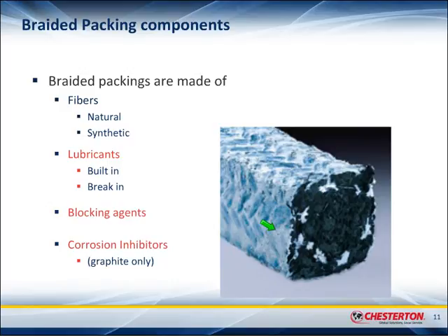What you have as well are break-in lubricants, and you can see break-in lubricants very well on this picture here on the right. That is the lubricant that is applied to the packing after it has been braided. After the braiding has taken place, some lubricant is put on the outside of the packing that assists for the first 15 minutes of running, so it can nicely conform in the stuffing box and gives the necessary lubrication for the first 10-15 minutes of operation.